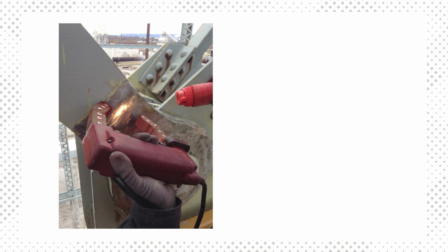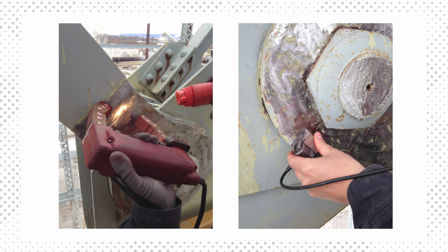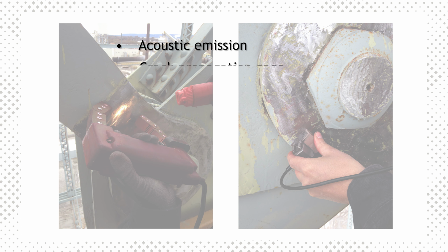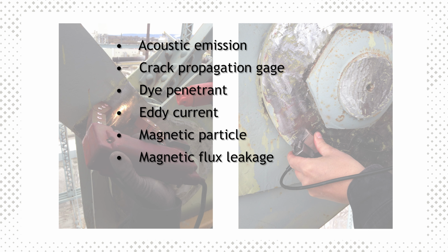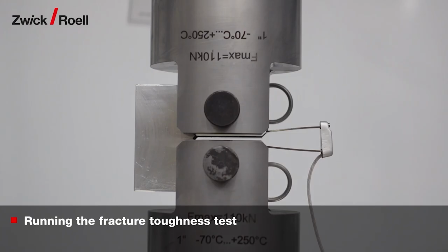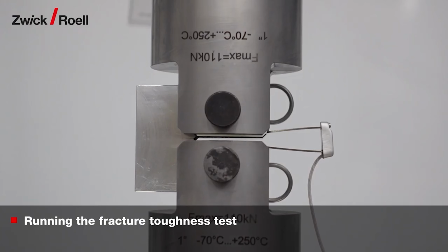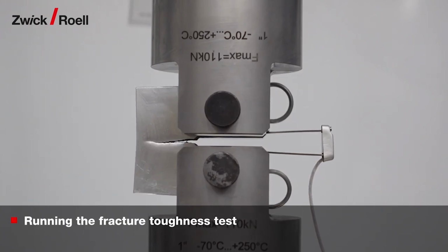When visual inspection isn't sufficient, advanced inspection techniques are required. These include acoustic emission, crack propagation gauge, dye penetrant, eddy current, magnetic particle, magnetic flux leakage, ultrasonic, and phased array ultrasonic. An alternative to the safe and infinite life design methodologies is fracture mechanics-based design and evaluation.